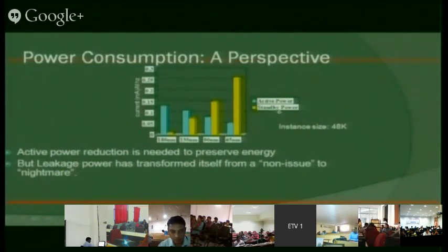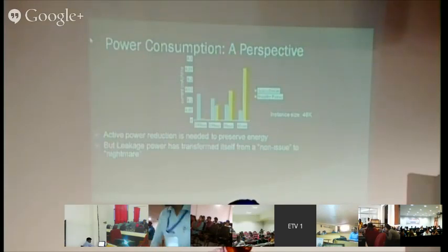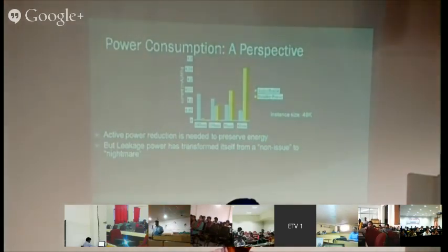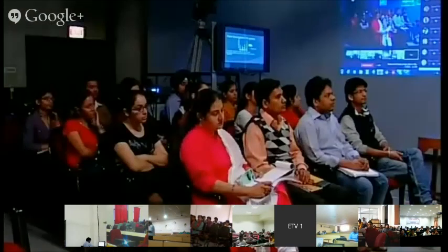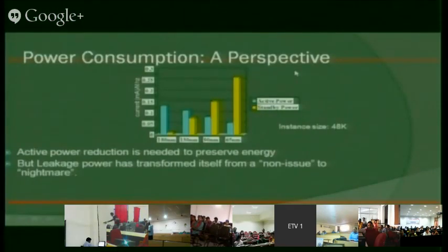Leakage power, standby power, is also known as leakage. It is called leakage because if the chip is not working, not functioning, and is on standby mode, it should not take any power. So we call it a leakage. Fine. So leakage, which was not there in 180 nanometer, in the lower technology nodes has become a nightmare. You have to control it.